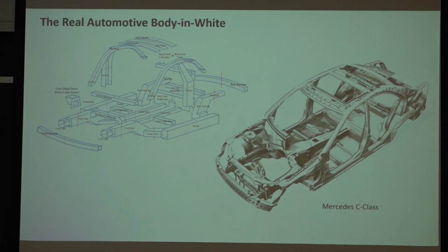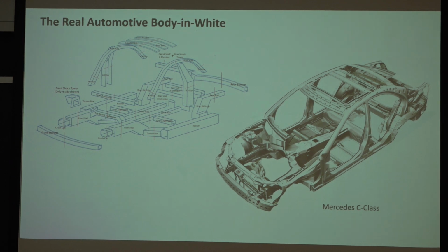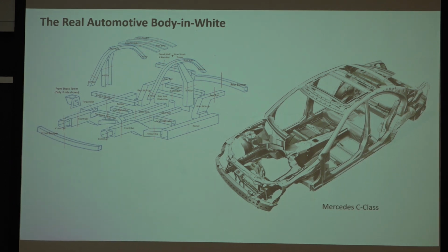Most cars today actually have what's called a crush can. It goes between the front rails and the bumper, and they usually make this part out of aluminum. They take advantage of some of the deformation mechanisms in the aluminum to absorb more energy in a front impact.